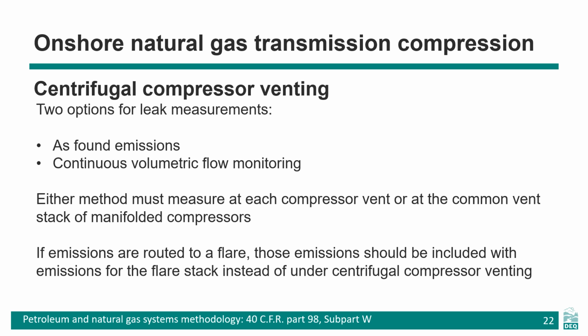For centrifugal compressor leak measurements, there are 2 options: as-found measurements or continuous volumetric flow monitoring. Measurements in either mode must be taken at the compressor vent or at the common vent stack of manifolded compressors. For a manifolded group, measurement can be taken from a single point in the manifold downstream of the compressor inputs. This measurement should occur before any commingling with other non-compressor emission sources, if possible. If emissions are routed to a flare, those emissions should be included in the emissions for the flare stack instead of under this emission source.